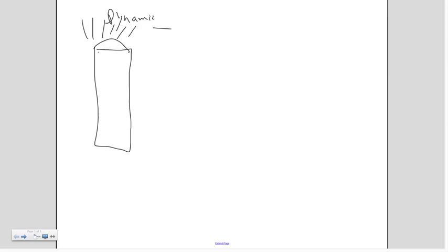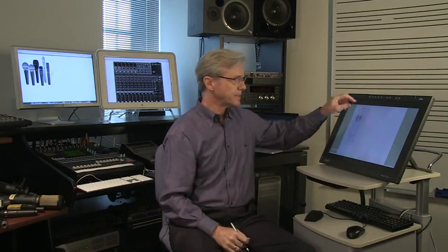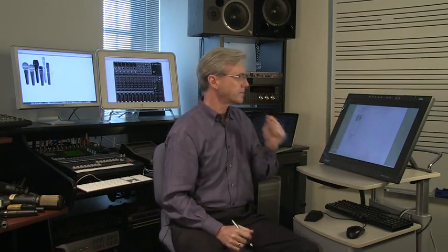That diaphragm then, which you'll have inside here, is a copper wire, that moving coil, and around that will be a magnet. And then the magnet obviously has a positive and a negative charge to the magnetic energy. As this diaphragm moves that coil of copper, as the copper moves closer within that magnetic field, it will then send a positive and negative electrical charge out the cable. So what we've got is a conversion of the acoustic energy into an electrical signal, which will then convert us into patterns of alternating current.